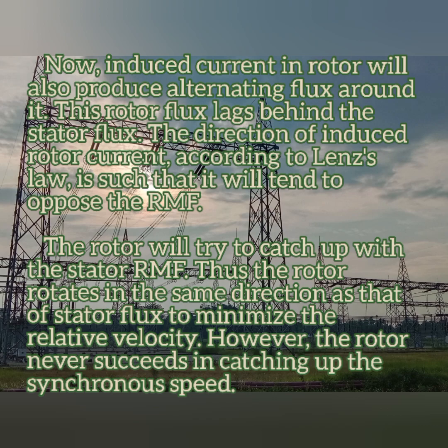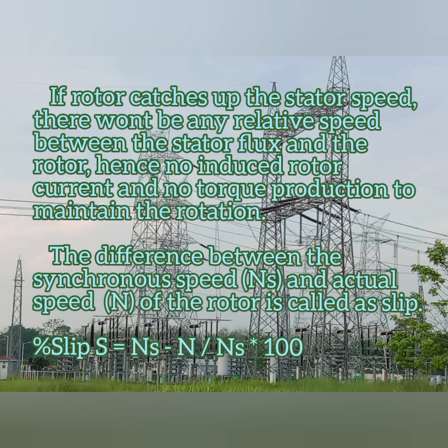The direction of the induced rotor current is according to Lenz's law, which means the rotating magnetic field produced by the stator and the induced EMF produced by the rotor oppose each other. So the rotor will try to catch up with the stator RMF. Thus the rotor rotates in the same direction as the stator flux to minimize this relative velocity. However, the rotor will never succeed in catching the synchronous speed.